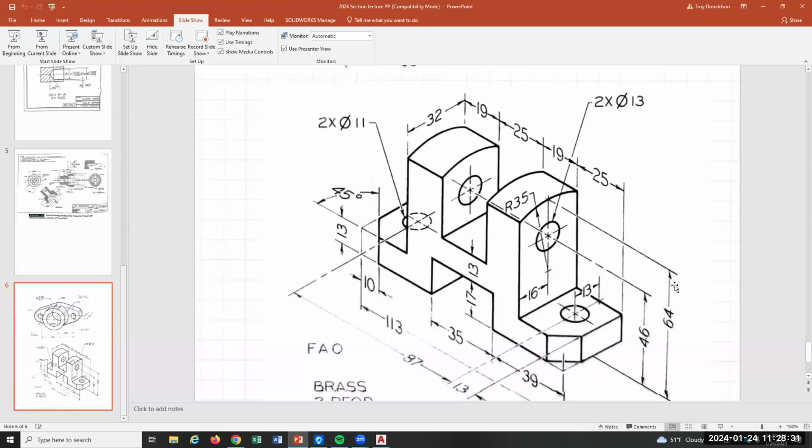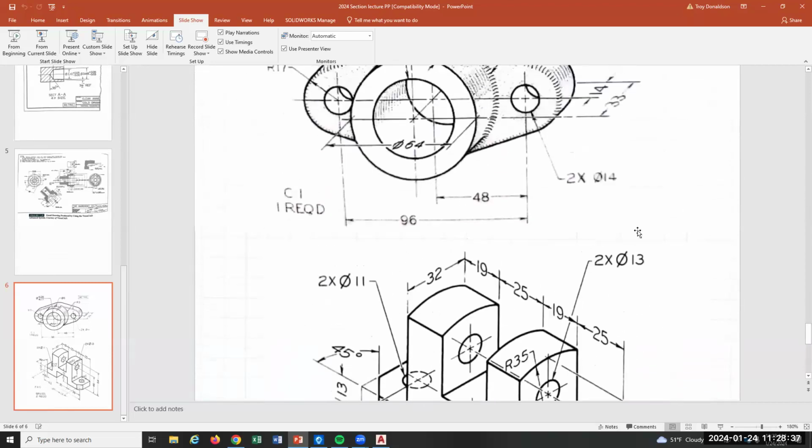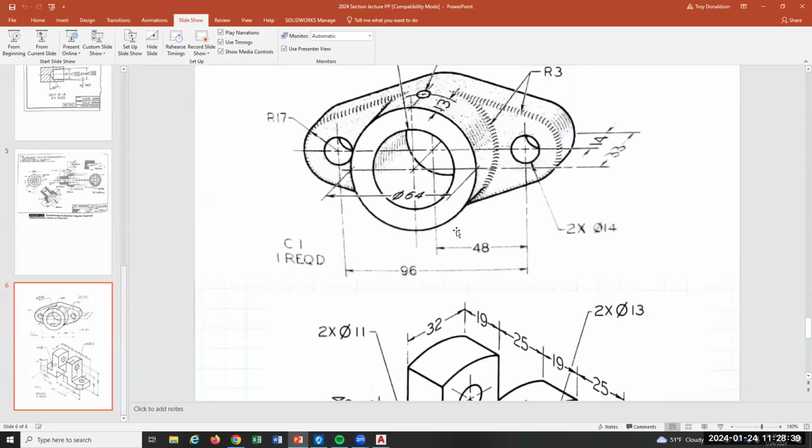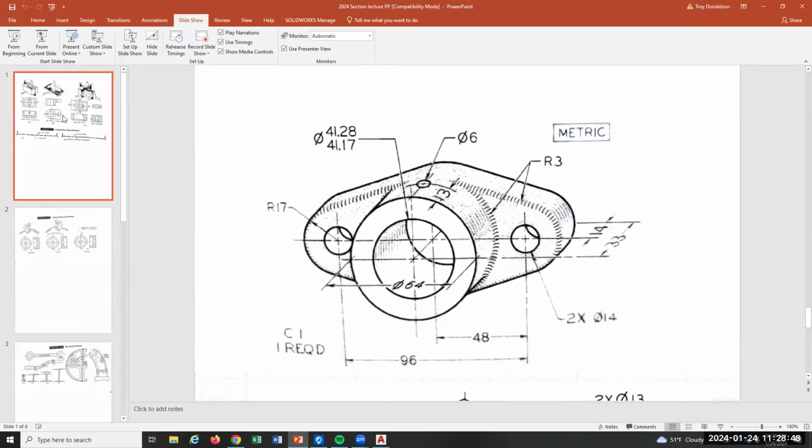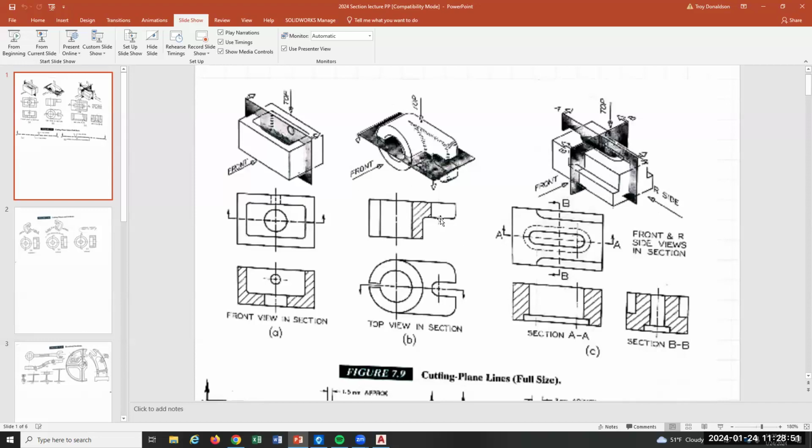So for example, if we're doing the front view, when we make our cut, we're going to show the front part of this piece. So what are we going to do for that area? Is there maybe hidden lines still? In the front view, for the second object? The second object is the section, so no hidden lines. In the section view, we're really focused on this inside geometry, not anything that happens back behind it. So we omit hidden lines in a section. Even if there is hidden geometry, we don't care about it. We're just going to draw that cut. Good question. That's important.